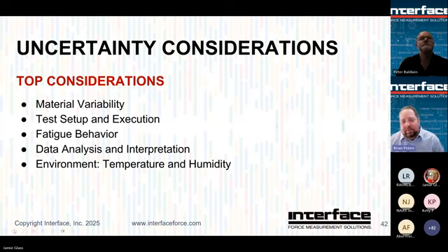And then how stable is your test environment? Is temperature changing? Is humidity changing? Any of those factors you want to keep in mind, again, because fatigue testing is often done over a much longer duration. Next slide.